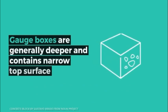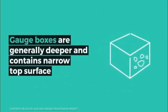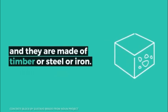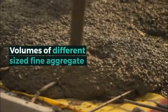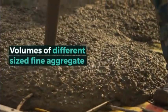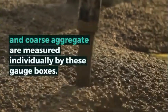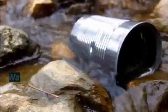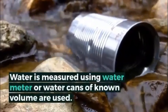Gauge boxes are generally deeper and contain a narrow top surface, and they are made of timber, steel, or iron. Volumes of different sized fine aggregate and coarse aggregate are measured individually by these gauge boxes. Water is measured using a water meter or water cans of known volume.